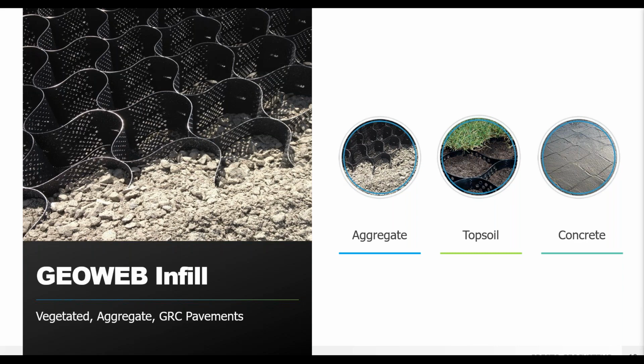The ability to use sands and low quality aggregates really sets the 3D GeoWeb system apart from things like planar geogrids or geotextiles. Both of those types of products require the use of high quality materials with very high friction angles to achieve their optimal performance. With the GeoWeb system, low friction angle materials are just fine. The GeoWeb panels still achieve their full potential even when using poor quality materials. So good cost savings options there.